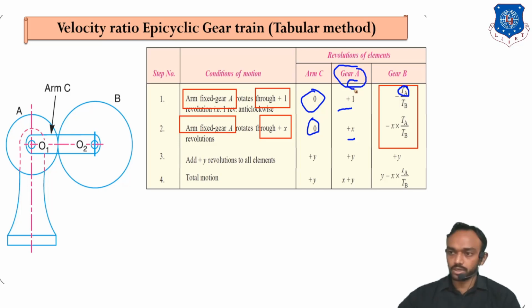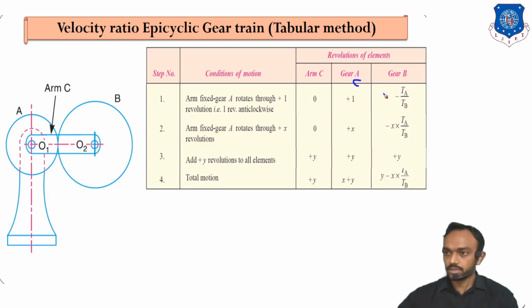If I am taking the gear C here, then here will be TC, because for the table there will be driver upon driven. Remember that in the table the teeth ratio always comes as driver upon driven. So whatever the gears are, the driver will always be considered this.